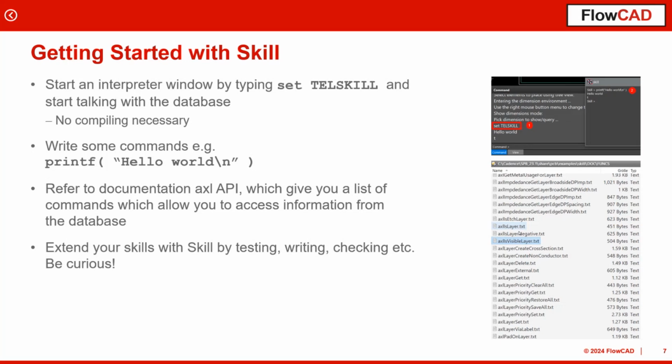Also, you don't need to worry about whether you use backslash or forward slash in your paths. In SKILL, everything can be expressed using forward slashes. So no need to worry about, oh, am I on Windows or am I on Linux? It doesn't really matter, because, as I mentioned, SKILL takes care of it. Completely platform independent. That is a big benefit.